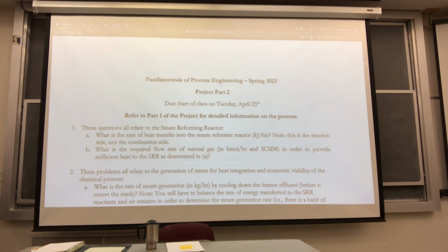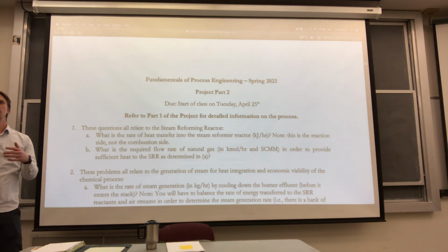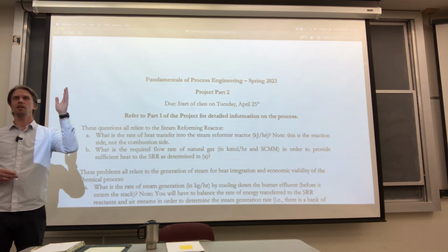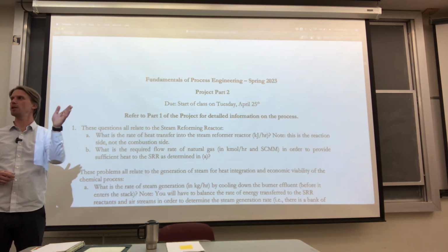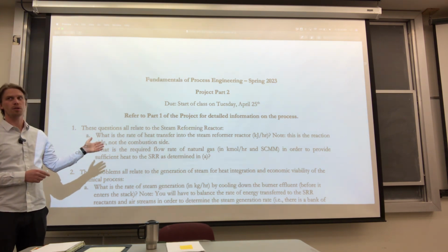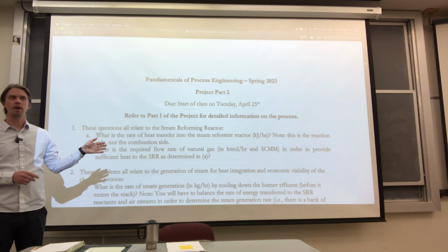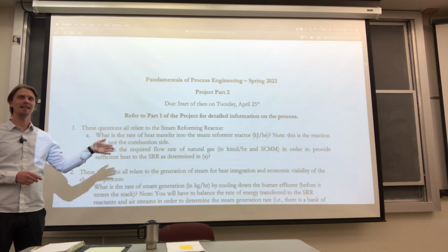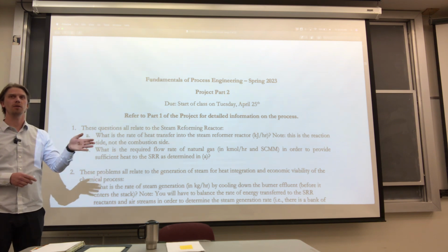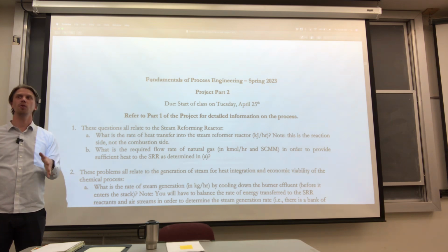All right, but the good news is that many of you on the exam did very well on the reaction balance problems. I think the algorithm is understandable. Choose heat of formation. The enthalpies are just heat of formation plus integrating C sub P dT. The good news is that you can do that for most all of these problems. So if you build one really good spreadsheet, then all you basically have to do is copy in the inlet streams, their inlet temperatures, the outlet streams, their outlet temperatures, and then you got Q. So they should go relatively straightforward.